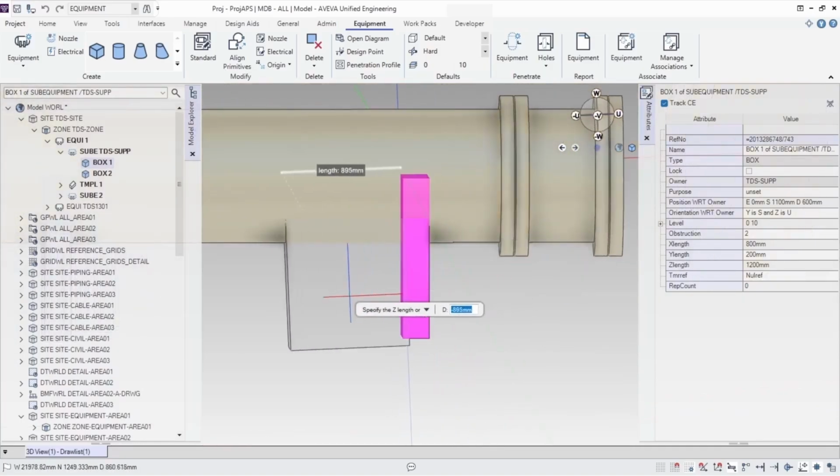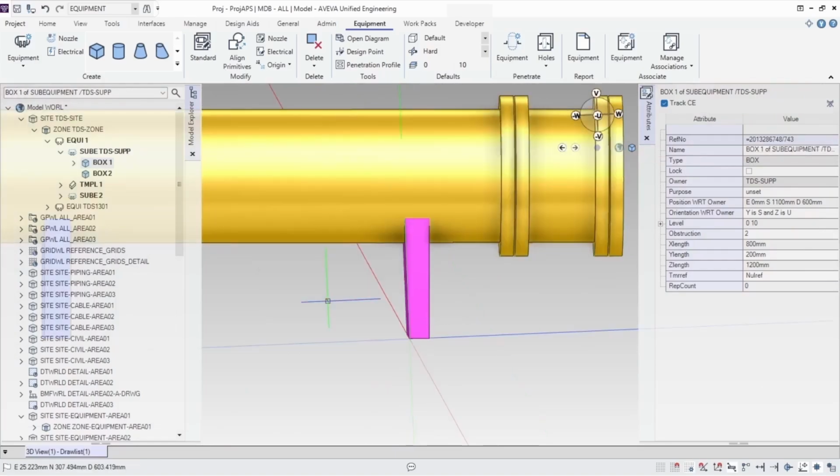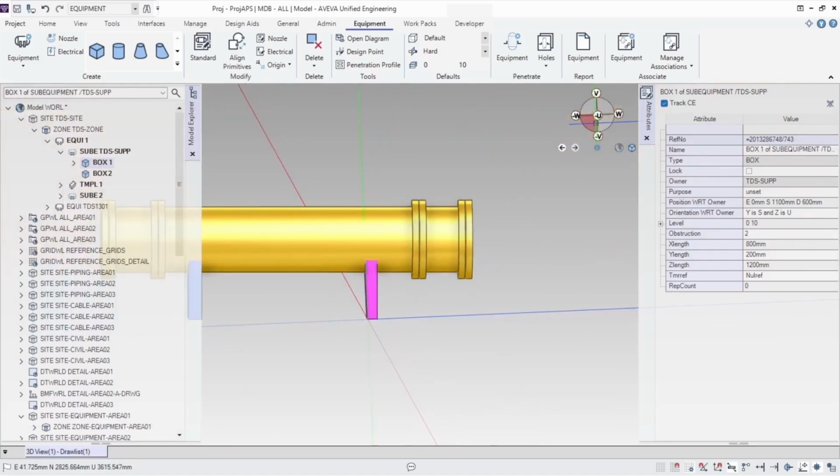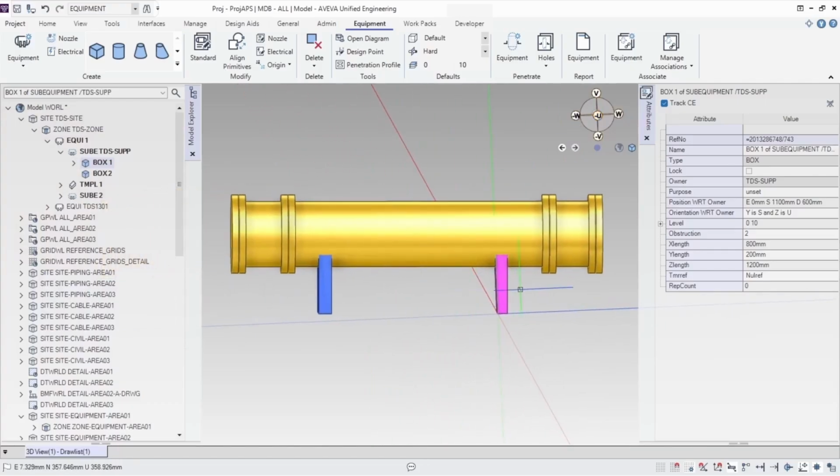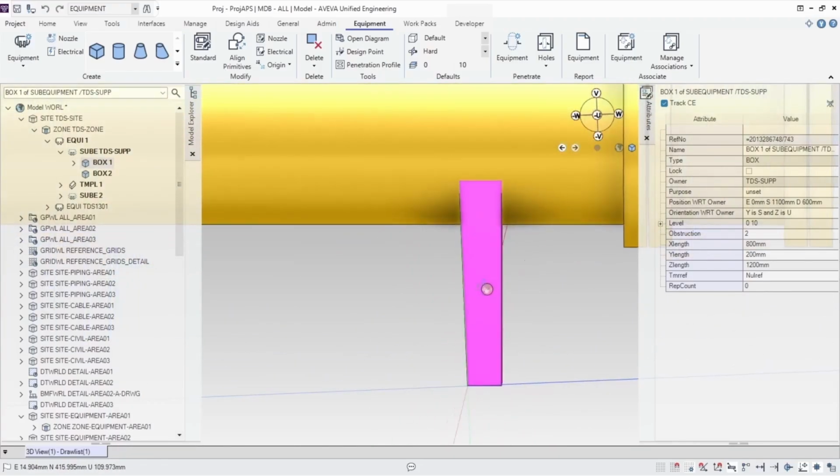Length. Enter -500 to extrude the negative box in the opposite direction of the LCS axis. After confirming, you'll see that a slice of the solid is removed. The cut follows the angled plane we defined with the LCS, giving the box its trapezoidal profile.